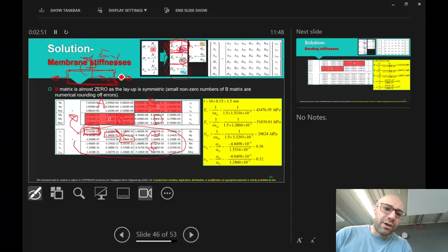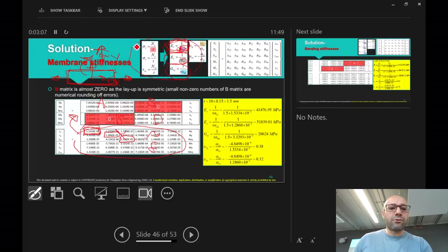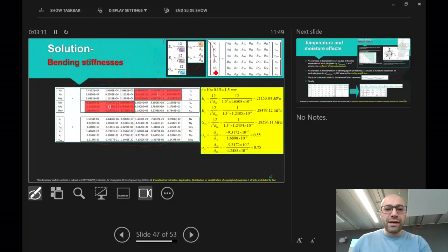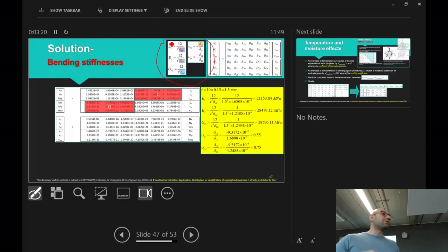In this particular case, you've got a tensile load, it could be compressive, or you can have another load perpendicular to that. But it is also well possible that your composite could undergo bending. Bending is not in the plane of the composite anymore. You cannot utilize these EXs and EYs for that kind of loading. For those, you need to make use of EX and EY for bending. It's a different category. This is something that many people, yet again, have a misconception about and make mistakes. So it's really down to your loading.